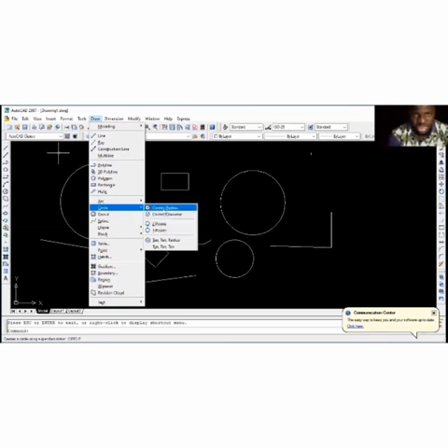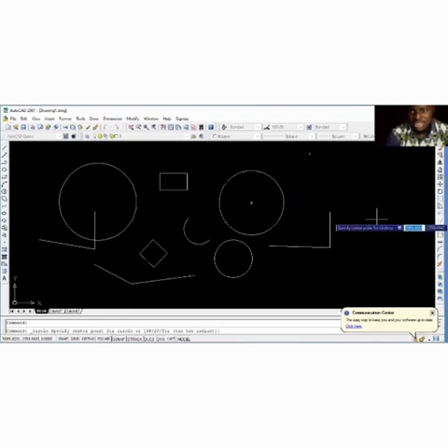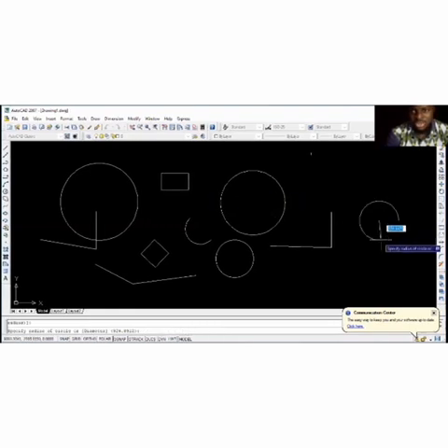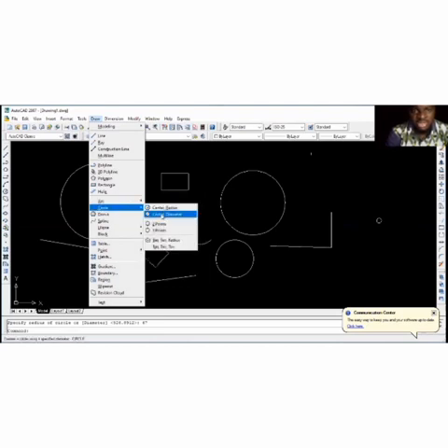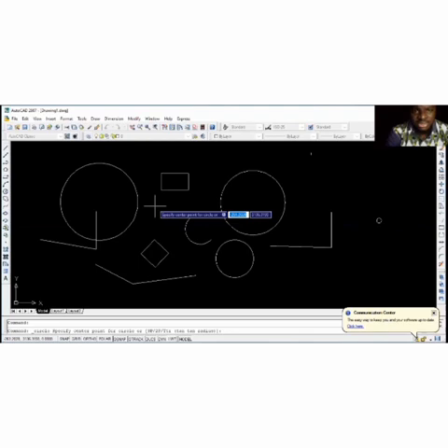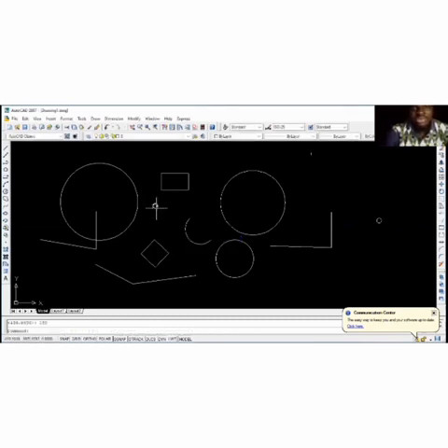For instance, if you pick center radius, click on it. It only means that you're going to select the center point and then choose the radius. Okay, let's choose a radius of 67, then enter. That is the radius. Get it? That's center radius. Okay, now let's take the draw again. We come to the circle command. Let's choose center diameter. Now we've taken our center. Okay. Now let's choose a diameter of 130.